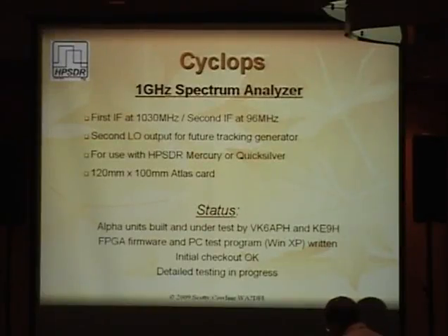Cyclops, he's a 1 gigahertz spectrum analyzer, first IF at 1030, second IF at 96, so it's a low second IF.